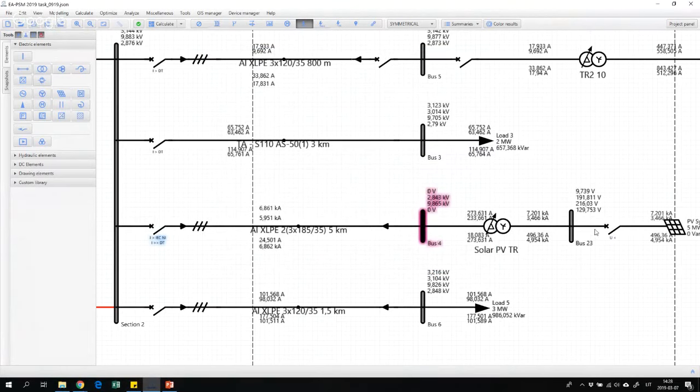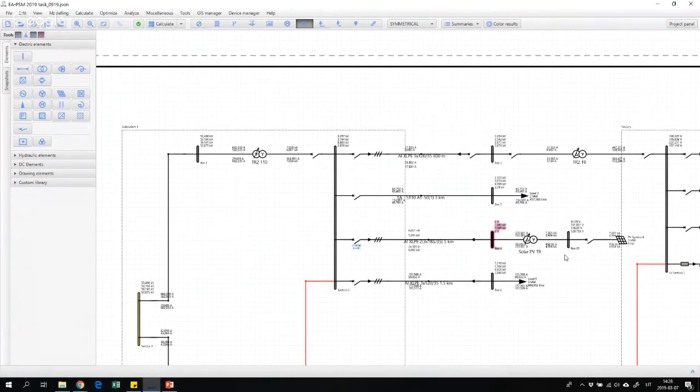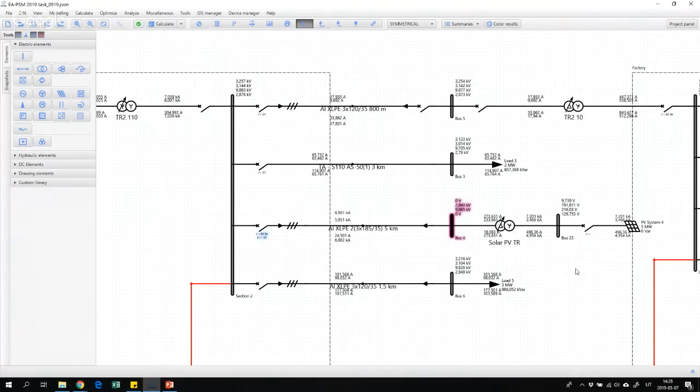But we cannot disconnect it instantaneously, because if we disconnect the solar power plant instantaneously after any fluctuation of voltage, it will cause instability of the network, because we will lose a power generator, and we will have to compensate that power from some other generation sources, usually thermoelectric power plants. They generate the biggest part of the consumed energy, so they will have to compensate this loss of power, and of course this can cause problems to the network.